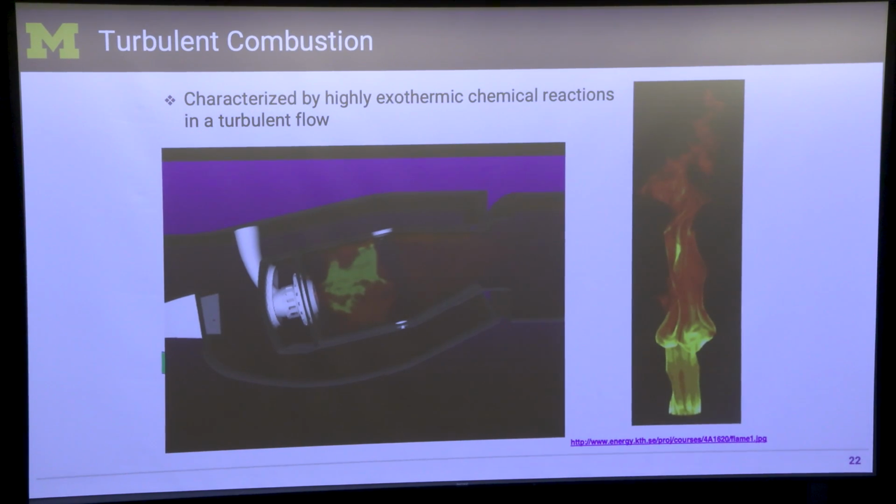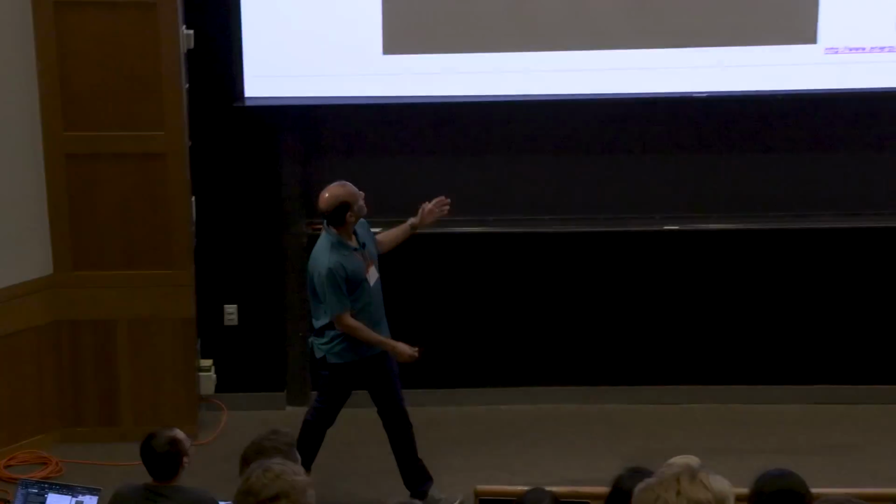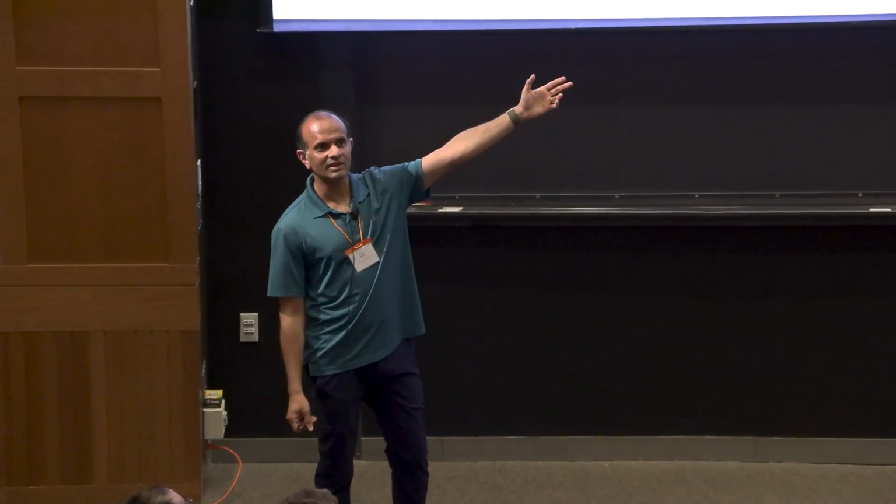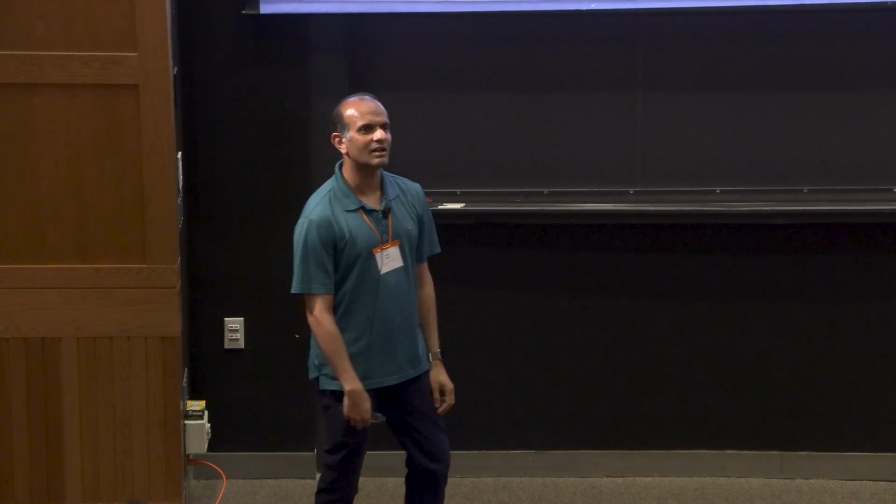And so this is what is called an RQL combustor. So you have a rich initial zone where you burn it very rich, right? Most military aircraft operate like this. Then you have this secondary air that's coming in, which quenches or reduces the fuel-air equivalence ratio. And then it gets it close to stoichiometric or something lower than that. And then you burn it lean further downstream. So that's the RQL design.